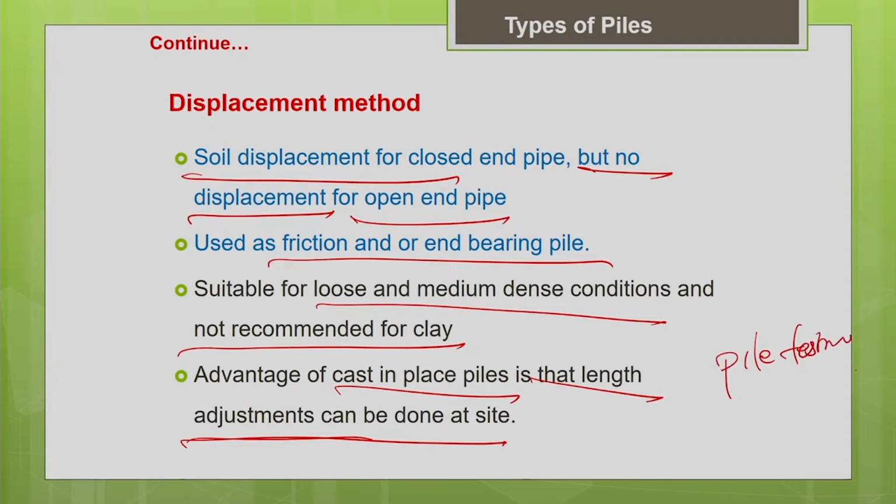So, you have to do some preliminary pile testing to know the exact length needed, and also to assess the load bearing capacity of the pile, and also you should carry out some geotechnical investigations to know the complete soil profile. So, you need to know where the end bearing strata is, and you need to carry out all the tests. Say, for example, the standard penetration test. All these tests will help you to know the soil behavior, which will help you in the pile design. That is why prior pile testing is very important before you do the actual piling operation in your project site.